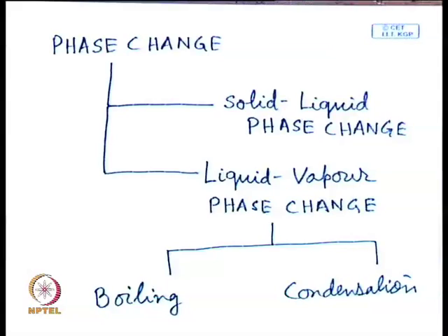Both boiling and condensation have many aspects in common with the two-phase flow situation which you have seen earlier. That means a gas-liquid two-phase flow where there are different kinds of flow regimes, and a different distribution of void fraction in a conduit.